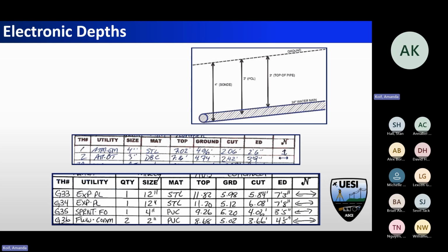And the reason for that, the diagram at the top is out of the standard. So you've got different ways that you're collecting data. If you use GPR, you're finding the top of that pipe with the GPR. If it's a bigger pipe, like here in this example, it's 24. So how's that CAD tech going to actually draw in that line? You've got data down to the top. Does he know that you're at the top, or is he just going to draw that circle in the middle of that line? So now you're just adding a foot difference or inaccuracy into your drawing by doing it that way, or assuming that that's the middle of the pipe.